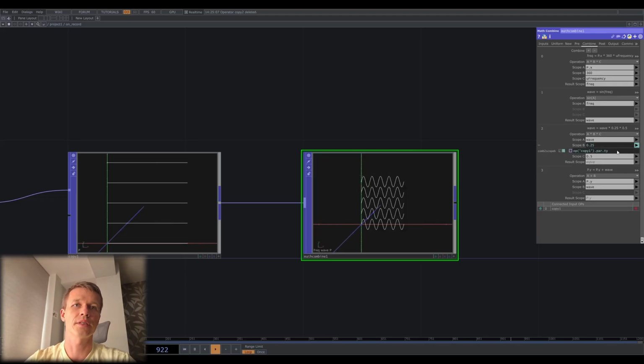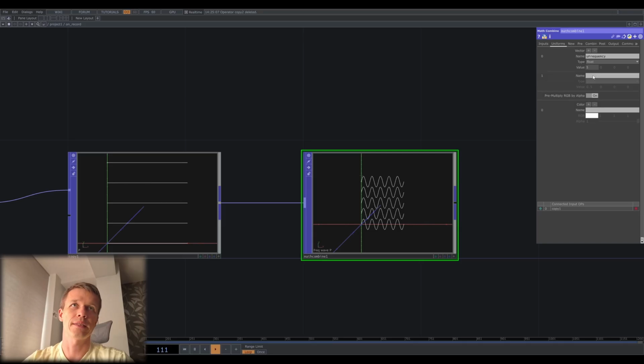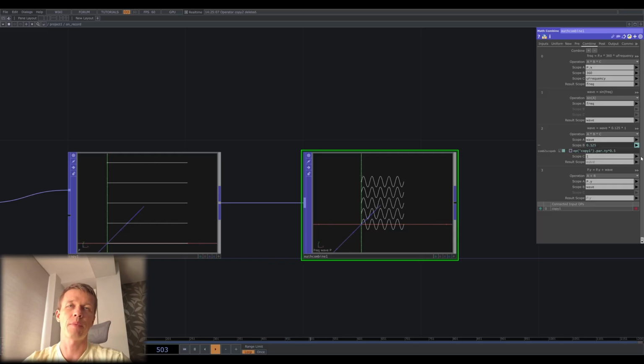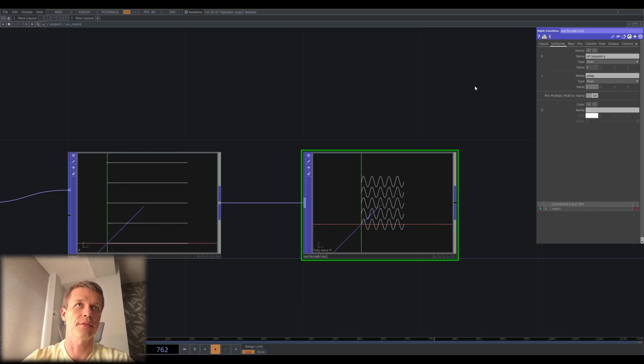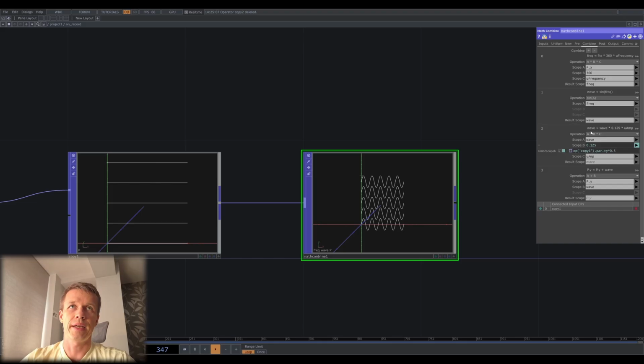So I will use the y translation value from the Copy POP as a reference. And now the amplitude of 1 means the wave occupies one full line gap in each direction. For this setup I will multiply it by 0.5, so each wave has half of the space between the two lines. Okay, and now I create u_amplitude, and this u_amplitude parameter is relative to the line spacing.